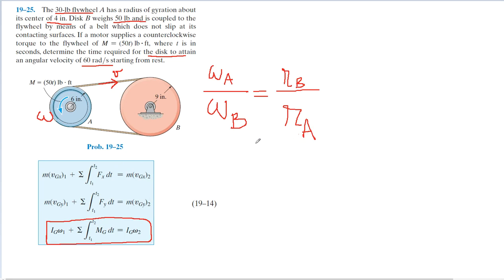Every person that's involved with mechanical engineering, not even engineers, knows that if you go from a small diameter to a larger diameter, there's a reduction in the transmission ratios inverse to the radii. So you know you are going to get an omega B that is less, so make sure that you use RA and RB such that by solving for omega B you get a smaller value than the input. Okay, anyway, the reasons are those explained.